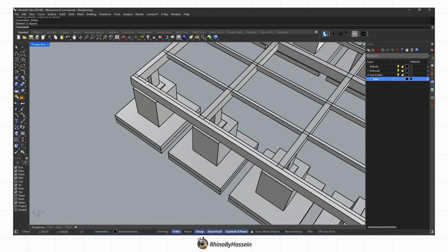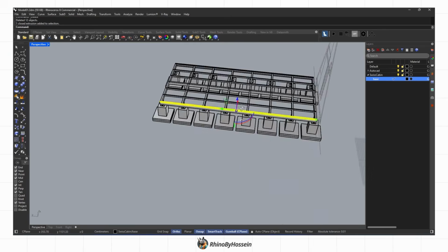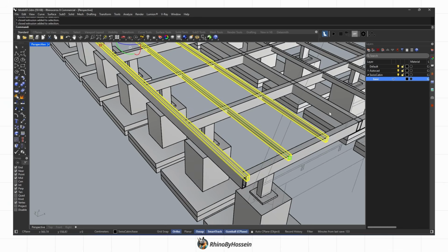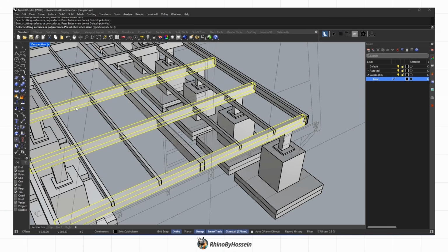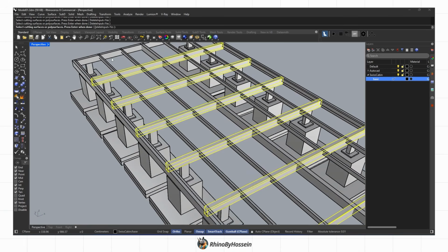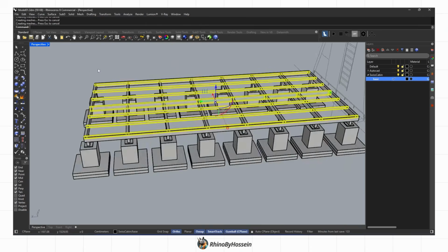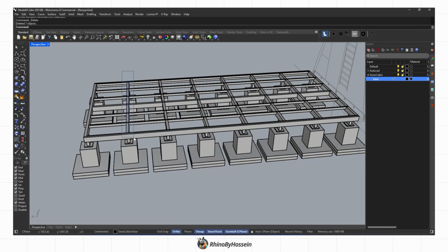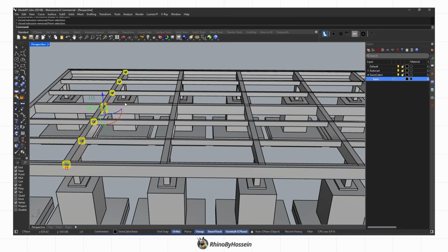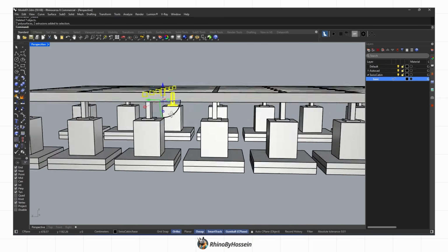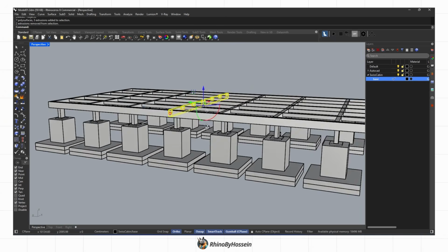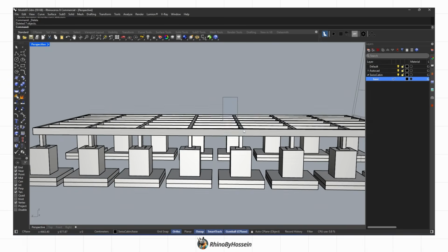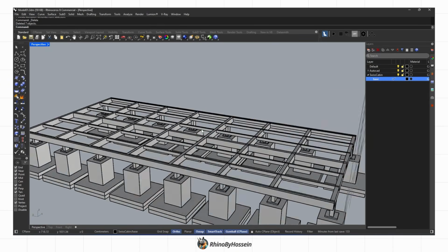To make the final model cleaner and more precise, and to avoid any geometric clashes between the beams, we use the Boolean split command. This removes the parts where the main transverse beams intersect with the beams we previously created. After this step, we select and delete the excess pieces that are separated. This process ensures that the intersection of the beams is completely clean and accurate, and the final model takes shape in an organized and precise way.